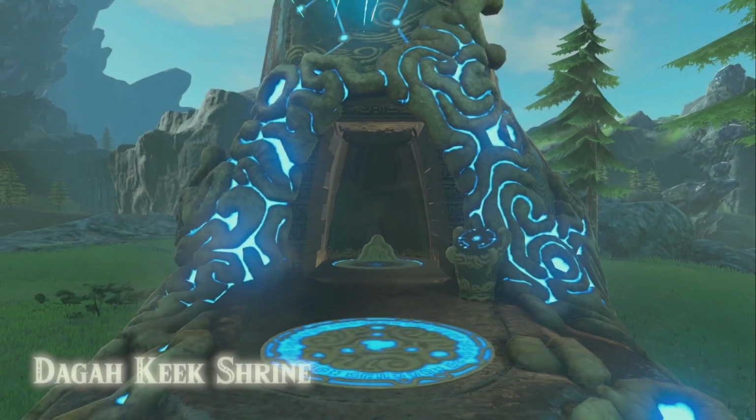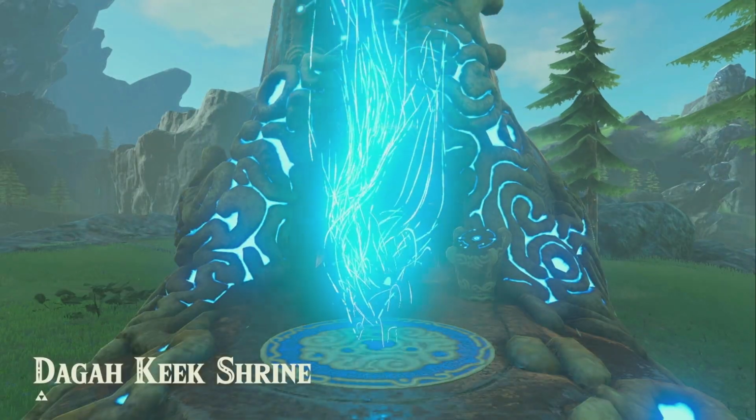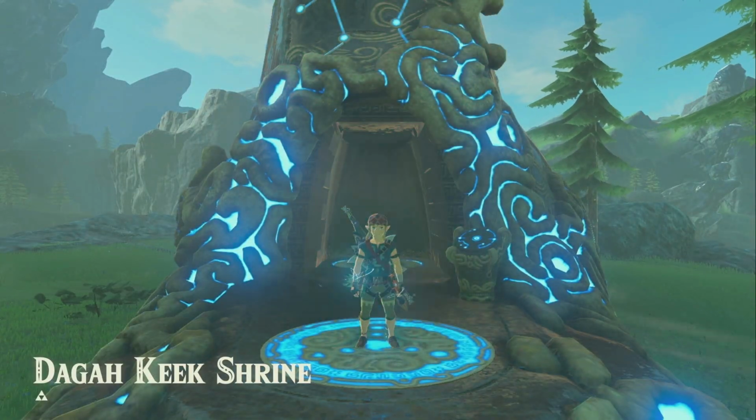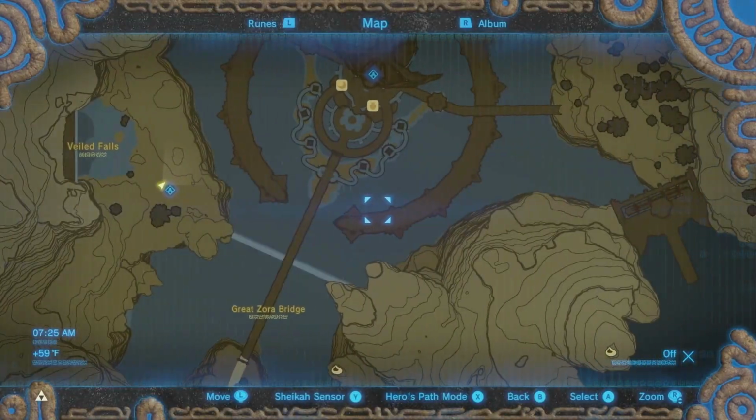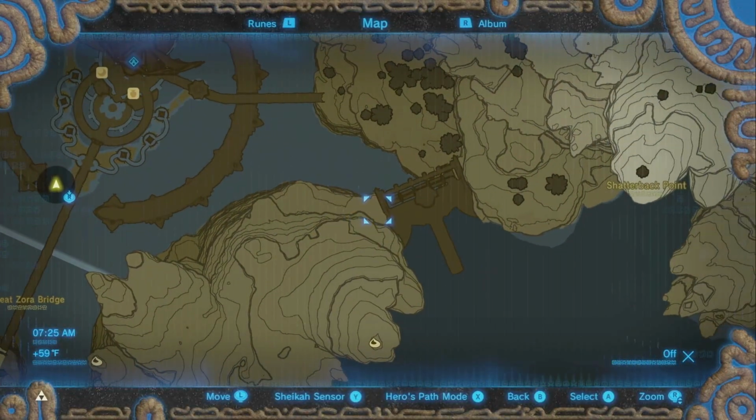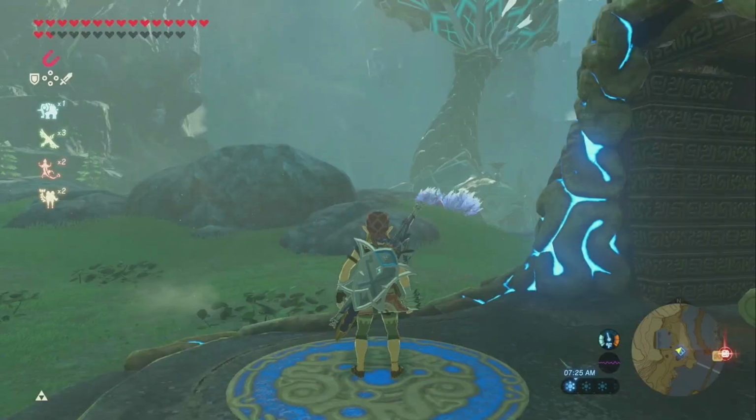Okay, the next picture, induced fan. These are not high efficiency. They allow venting through the side wall by dilution of combustion products with large volumes of indoor air.